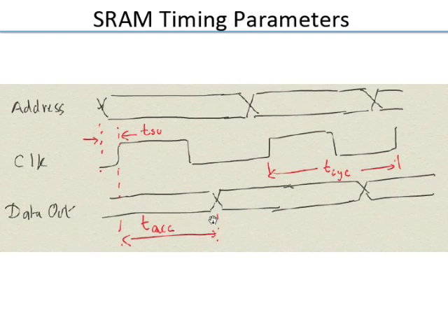So we have setup time, we have the access time, and we have the cycle time. Typically you are interested in reducing all of these because you want fast access. Speed of course is good from a performance perspective, but you can also trade off speed with power. If your friend has done a design which is faster than your design, that person can leverage that by reducing the voltage, for example, and slowing it down to meet your speed, hence consuming less power. So you can trade off speed and power, as we discussed when we were looking at power optimization.